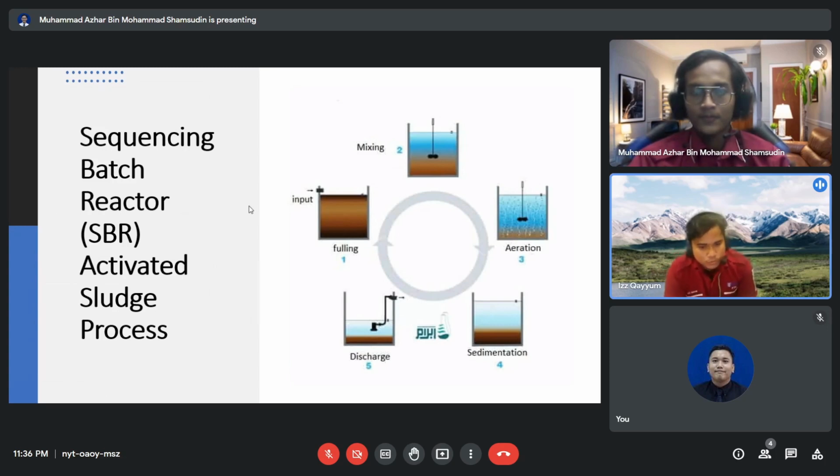I will explain in detail the wastewater treatment technology used in the textile industry. Many pollutant removal technological processes have been developed in the past decade to treat textile wastewater. The treatment processes are chosen on the basis of the composition, characteristics, and concentration of material present in the effluent. These processes are pre-treatment or preliminary, primary or physicochemical, secondary, tertiary, or combined treatment processes, depending on the type, sequence, and method of removal of the harmful and unacceptable constituents.